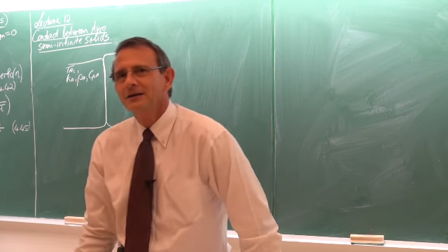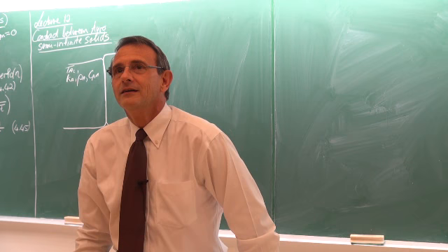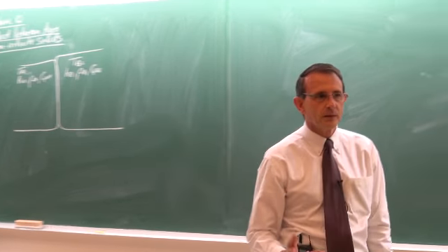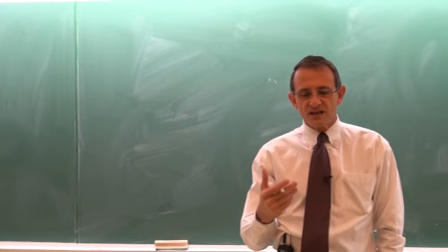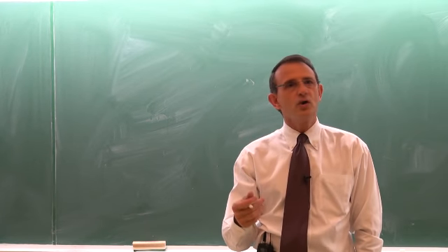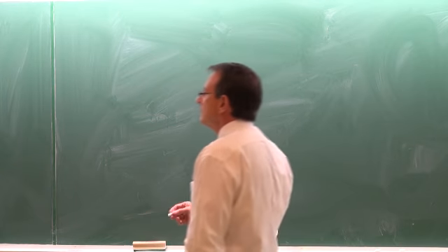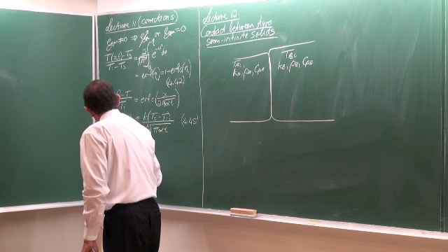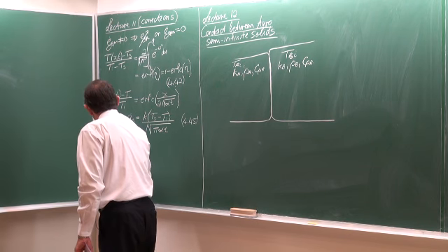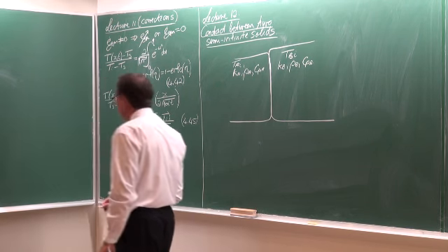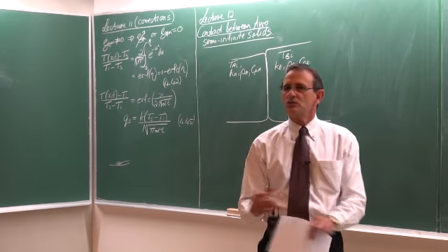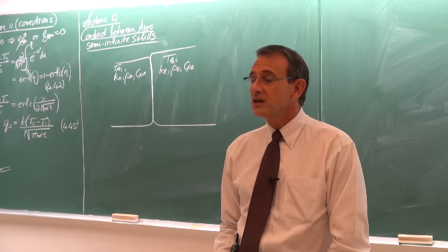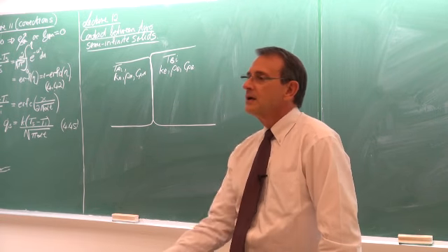Why do you disagree? It's exactly the same temperature. They are at exactly the same temperature. If you would take a thermocouple, put it on the surface of the bench, and put some insulation material over it, and you measure the 2 temperatures, you would see that they are exactly at the same temperature. Now, why does the one feel colder than the other?